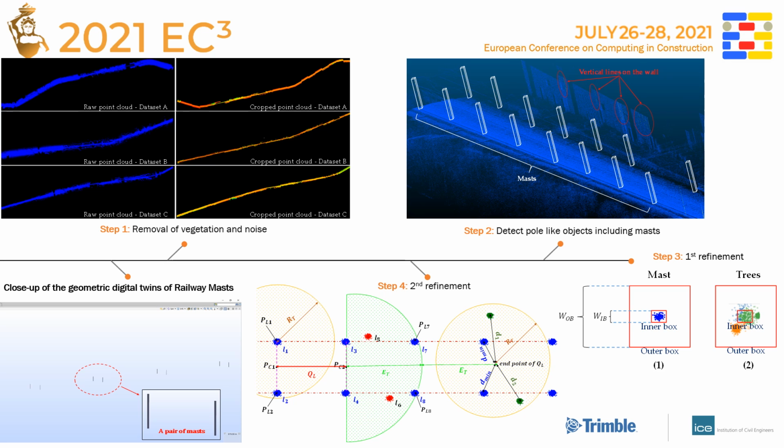That step was also needed to remove the vegetation from each of these small units. So once all the noise points are removed, the only vertical element parallel to the Z-axis should ideally be masts. So we used a line detection method to detect masts as lines. However, as there were a few other remaining tree trunks and a few vertical objects close to the rail track, the detection results were not sufficient to extract masts as point clusters.